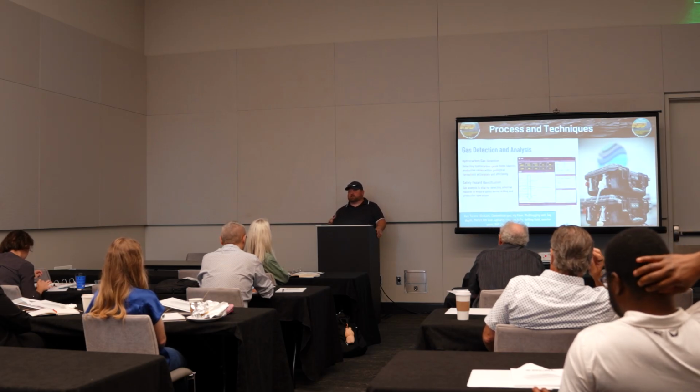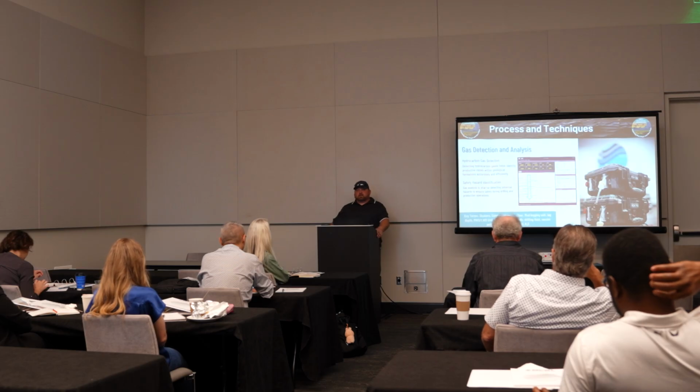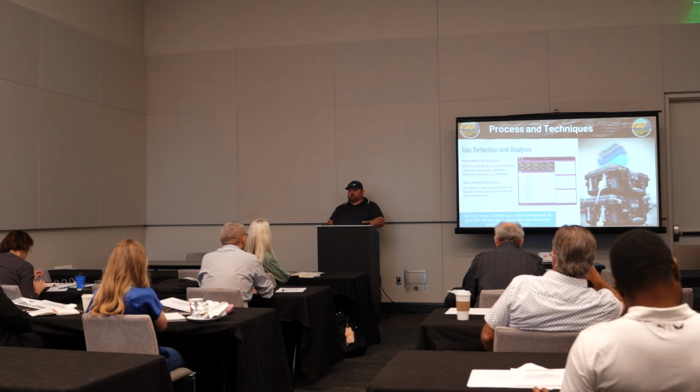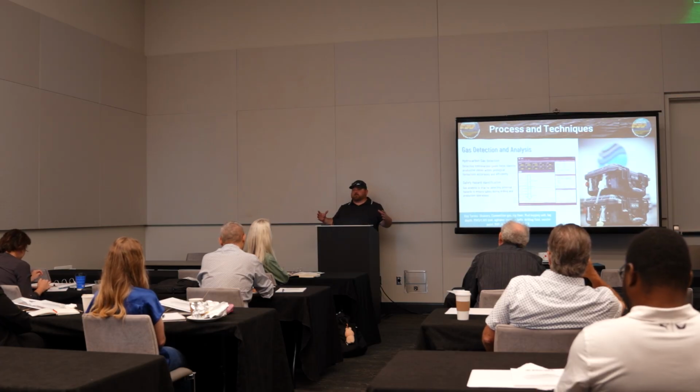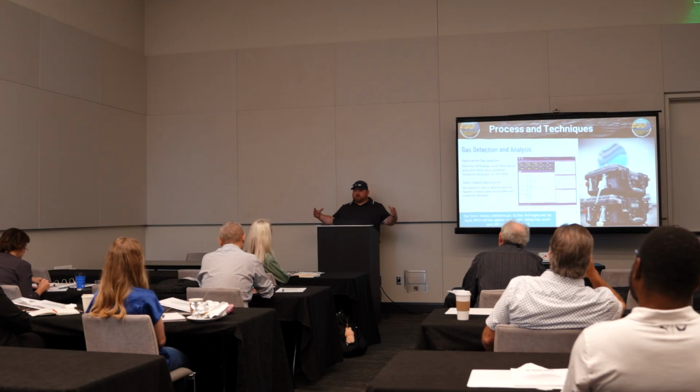That's what we're taking as connection gases, formation gases, downtimes. Connection gases are when the pumps are shut off and the fluid's static. The fluid just sitting there allows the formation, if the pressure is higher than the hydrostatic pressure on that particular formation, to allow an influx of gas and oil into the wellbore.